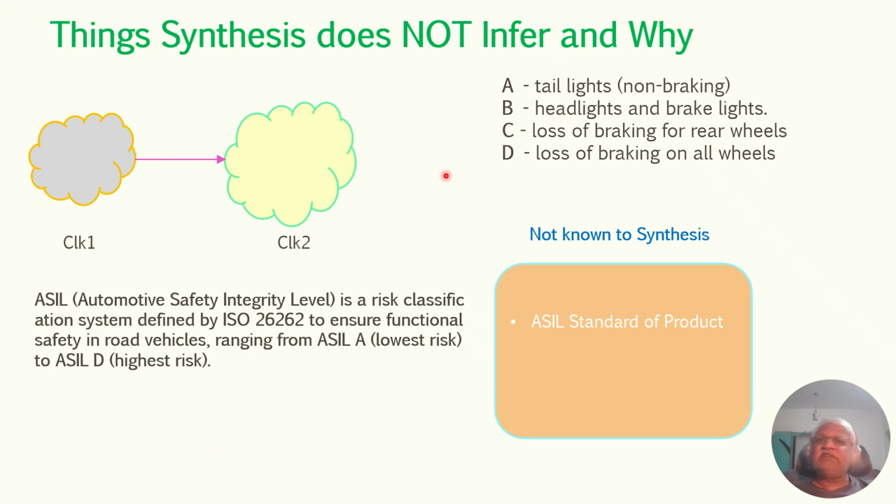So based on these things, how we figure out the various aspects of it, the ASIL and all, are very crucial. ASIL depends upon the exposure, which is the probability of exposure of this failure. It will also take into consideration the severity of the failure and how much controllability it has. That means it is not controllability of the chip, it is basically controllability of the driver of the vehicle where the chips are included.